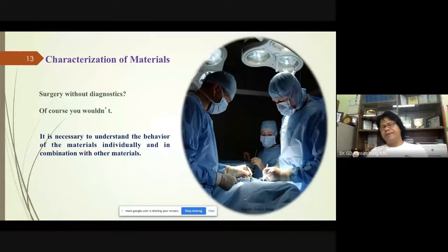Because we believe that if the degree of interlocking is very high, then we are going to get dense mixes, a dense aggregate skeleton. And if we get the dense skeleton, then the volume of paste we require would be lesser in comparison to open graded mixes, which are not well graded, for the same kind of aggregates, right? So proper investigation of the individual aggregates is imperative.